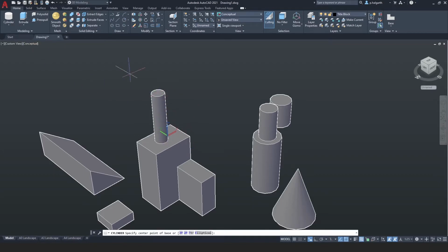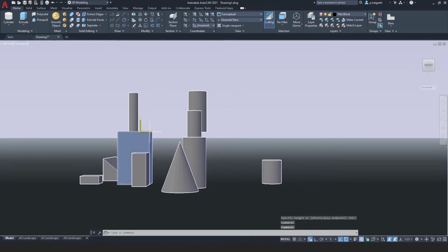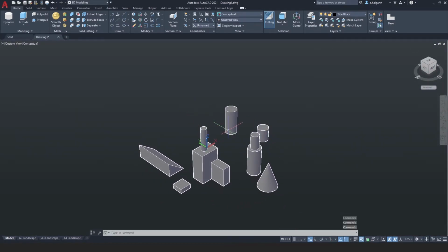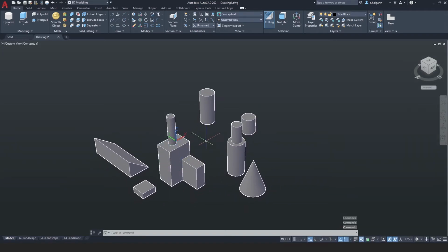That means that whenever I draw now, everything is going to be at that level. Even if I draw over here, you can see, if I just move this around to the front, that now I'm drawing up at this level always. So that's great. That face tool allows me to line it up with any face.